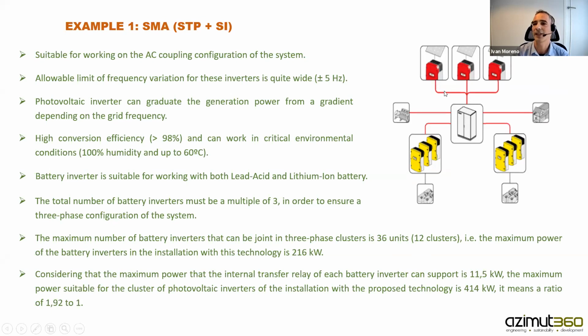So the battery inverters know how to manage the PV plant. If the battery is full, the load consumption is low, and the PV production is high, we have to fit that PV production to the current status, that we don't need much energy. So the battery inverter raises the frequency a bit, and the PV plant reduces the production gradually.